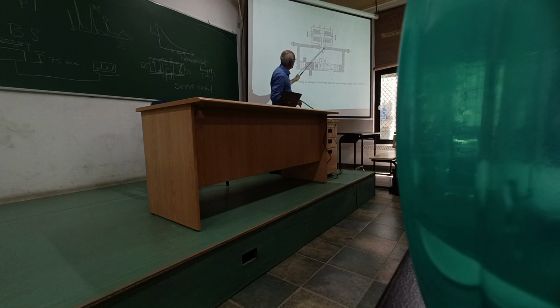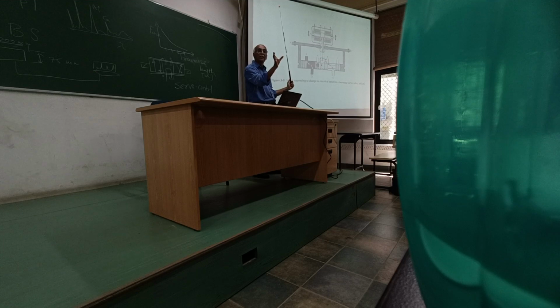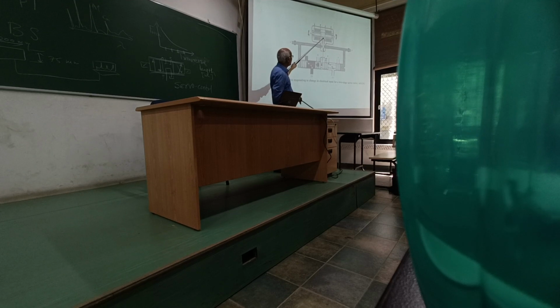There is a nozzle located over here, and fluid also gets directed to this place. The pressure P on both sides is equal, so the spool remains in a static condition. Now these nozzles are open in front, and in front of them there is a flapper.